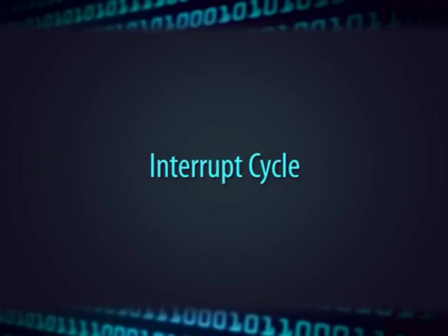The next cycle is the interrupt cycle. We have discussed the fetch cycle and fetch operand cycle so far, and the next cycle is the interrupt cycle. At the end of every instruction completion, all the interrupt signals are checked. If any interrupt signal is enabled by an external device, the interrupt cycle occurs, else the next instruction in the sequence is executed.